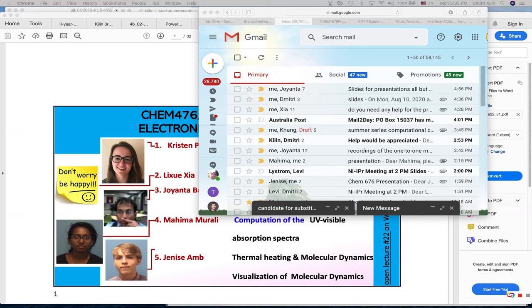In the content of the POSCAR, we usually have about 10 parts. What I think is most important is that we can change the relaxation state of all the atoms, changing T to F to fix the atoms or to relax them.